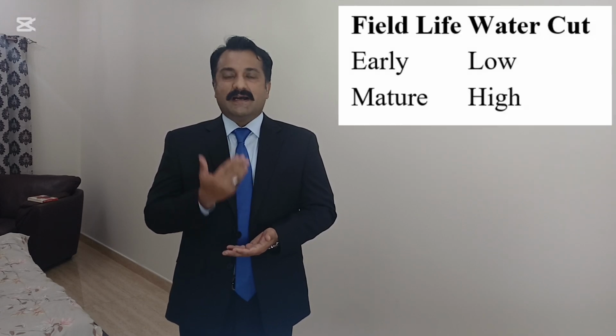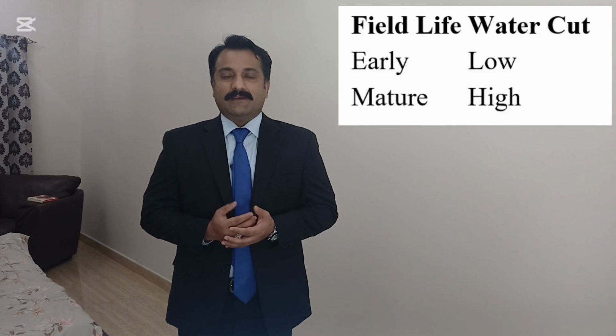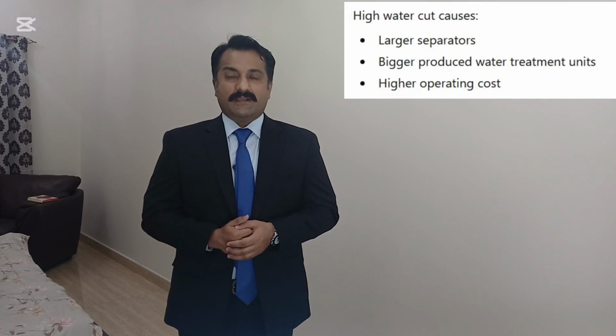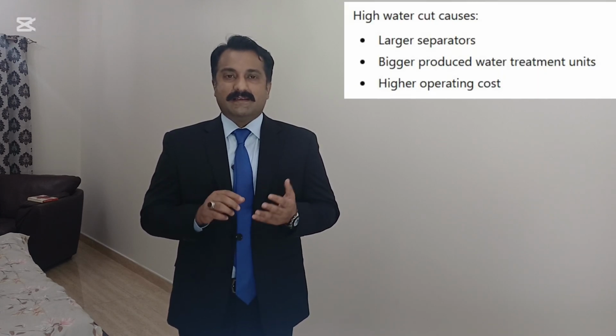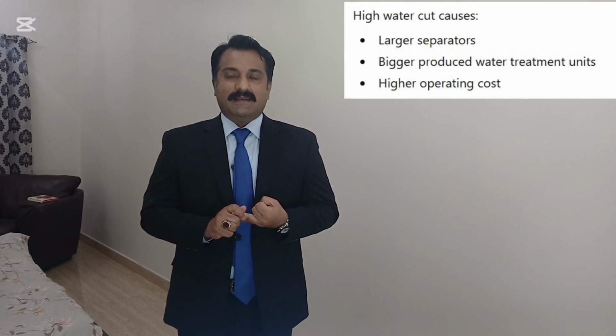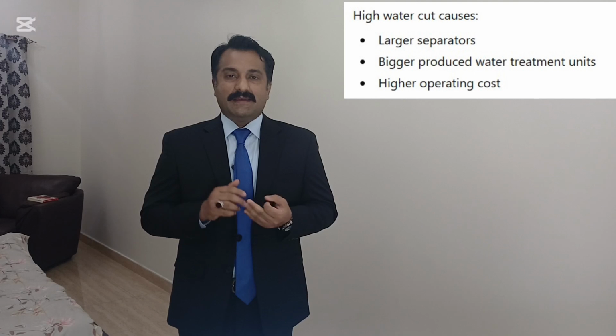If water cut is higher, then the well is mature. If water cut is lower, it means the well is new, early field. Higher water cut will cause a big separator size, a large produced water treatment plant, and higher operating cost.